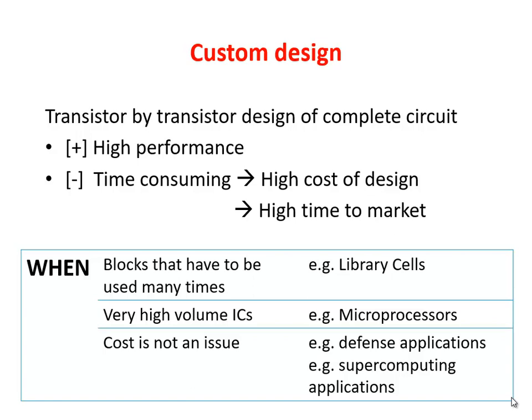Okay, for sure, independently of the cost, it is used for blocks that have to be used many times. So, for example, all the standard cells and the macrocells have to be designed transistor by transistor with custom design. So the design of standard cells and of macrocells, the so-called library cells, is done with custom design. You also do custom design when you have a very large number of integrated circuits.